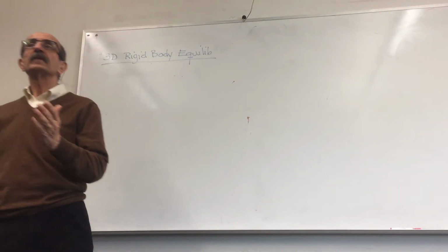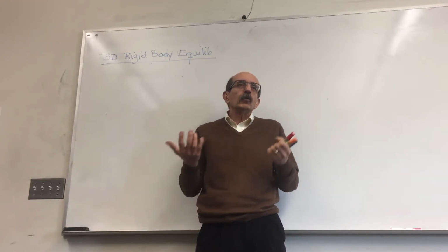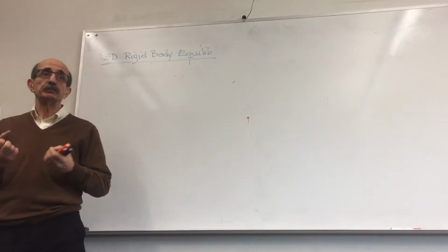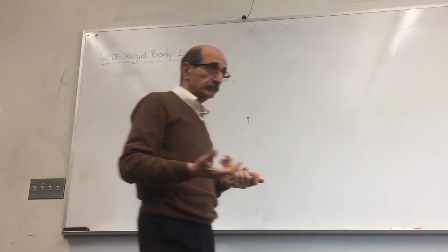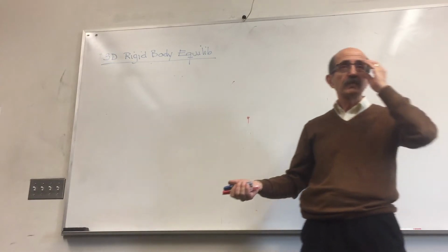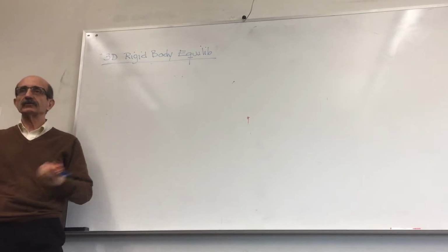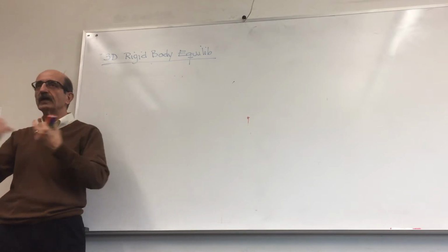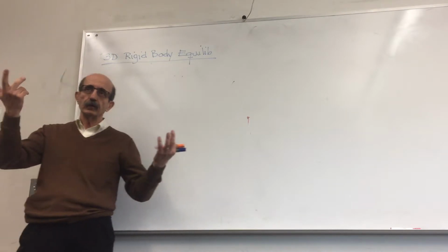In 2D, when we talk about support mechanisms, we have only three possibilities for how those mechanisms would prevent motion. They either allow motion in only one direction, two directions, or three directions, right? That's it. If rotation and translational motion are allowed and one direction is prevented, that was a roller. If rotation is allowed, two translations not, that is a pin. And if nothing is allowed, we have three unknowns, two forces and a moment.